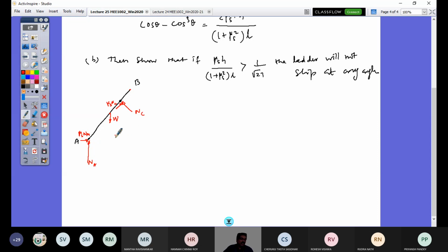But instead of that, in such cases it is convenient not to combine and to apply the conditions of equilibrium. So I'm just going to do this without combining, without applying Lami's theorem. One can also do it that way; I ask you to work it out. So now let's look at what my equilibrium equations are. Sigma Fx equal to 0, when I apply, I have here mu s NA, and here these two are inclined, so I'll have 2 components. So what is this direction? This is normal to this, and that will have, to the vertical, the same angle as there is here.